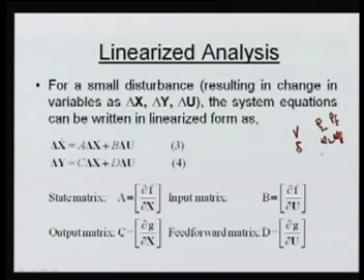We can calculate the reactive power generation of all the buses, especially in generators. So these two are the state elements, you can say states of the power system, that is, steady state information. So these two are the minimum. I am not saying that we can get all the information. So here V and delta are the state variables for the steady state.